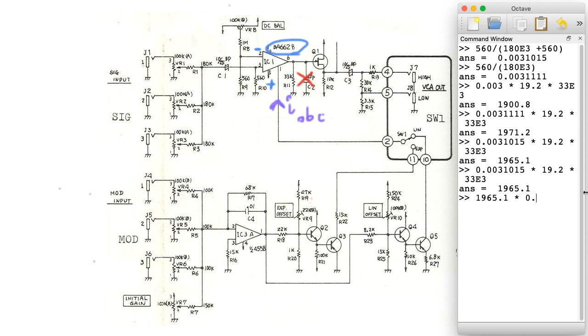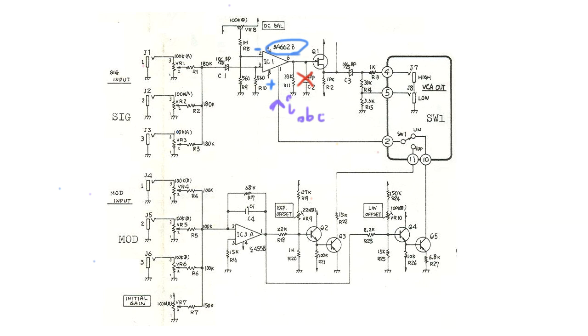So that's nearly 1. If this circuitry down here creates 0.5 milliamps, which is sort of a nice number, then you get unity gain or something close enough to unity gain through this VCA. I'll probably guess that that is what you would get if you have this knob turned all the way up. But again, that's just a hypothesis.